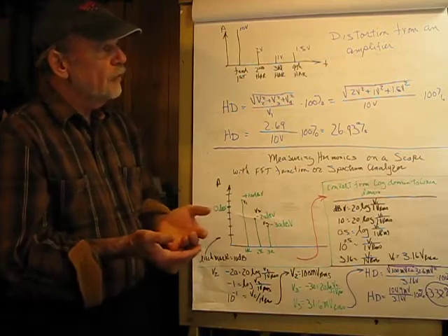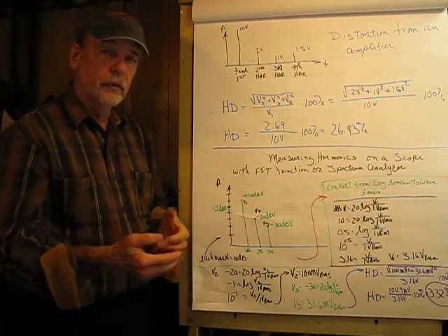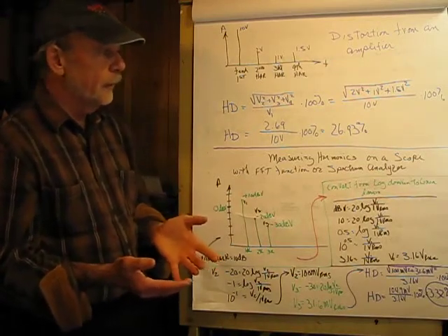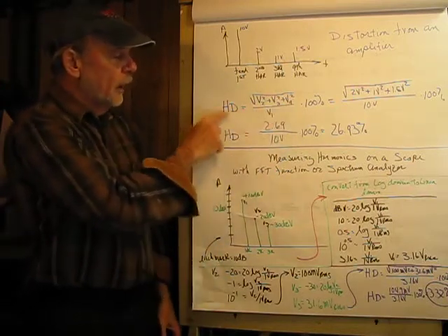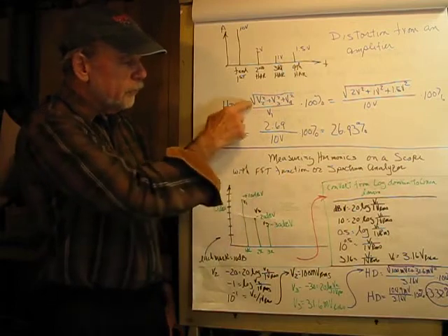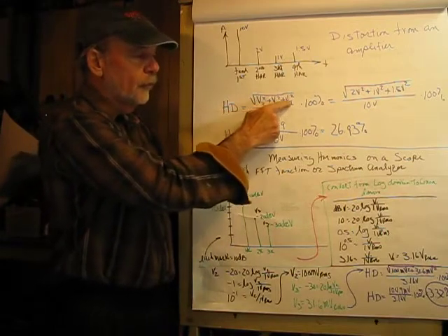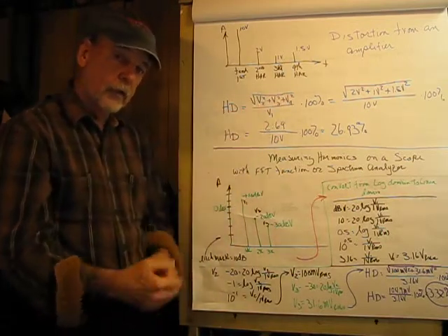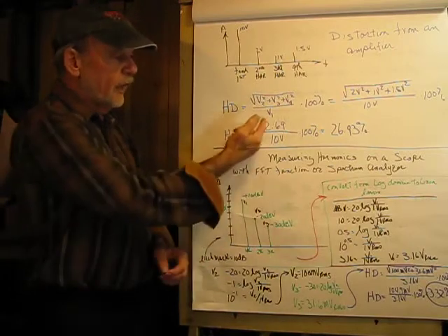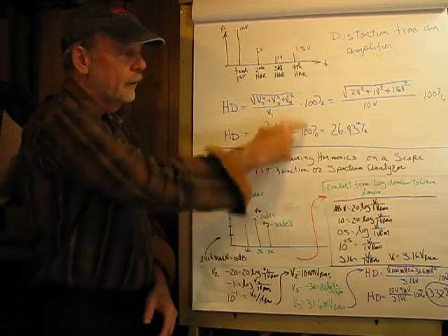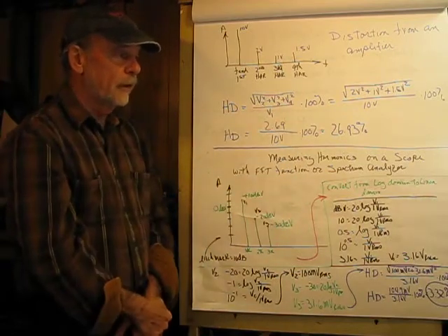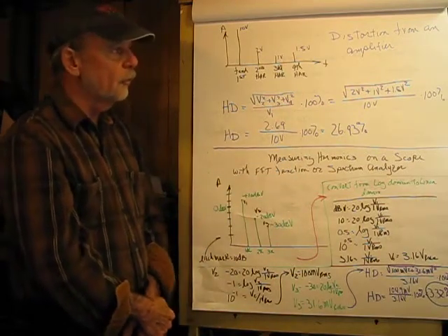Next thing is, how does the industry measure distortion? And the answer is that they have designed this equation as such. Harmonic distortion equals the square root of the sum of the squares for all of the harmonic voltages divided by the fundamental, and to express that as a percent, it's times 100%, and it could also be expressed in decibels.